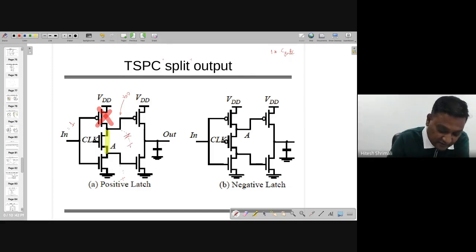Previously I charged it at VDD, and when in equals 1, fortunately it makes the connection, right? So in that case this VDD will go to 0, and accordingly this is 0, so output is actually VDD. But in the other case, whatever was the previous value over here, accordingly you can have the output. So you can observe that and find out if there is any problem associated with this one.